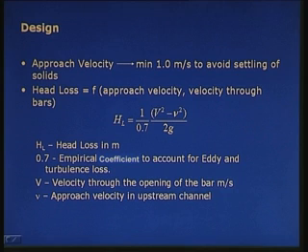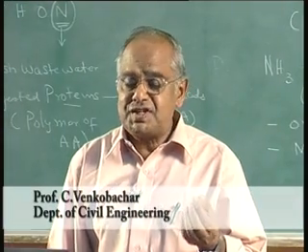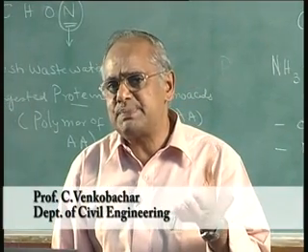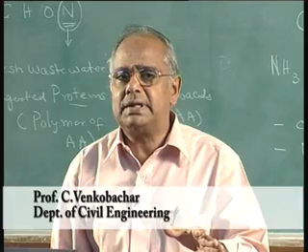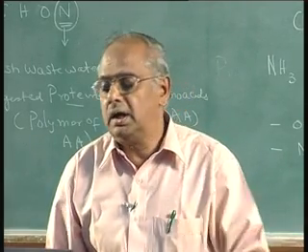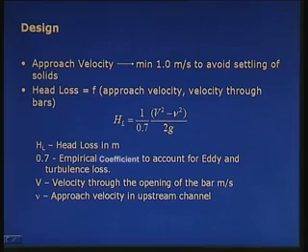If you do not maintain a velocity sufficient for the particles to remain in suspension, then what would happen? The particles will settle down in the channel, and once they settle, the carrying capacity of the channel is reduced, and the solids then biodegrade and cause lots of nuisance. That is why a minimum of 1 meter per second velocity should be maintained to avoid settling.